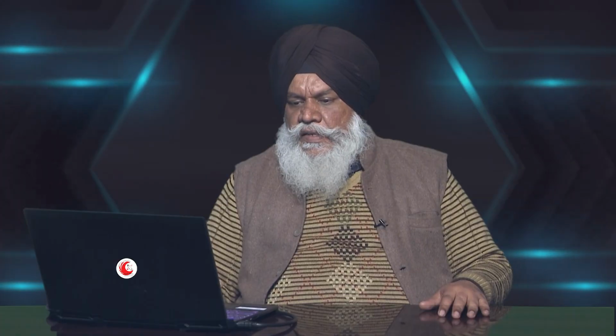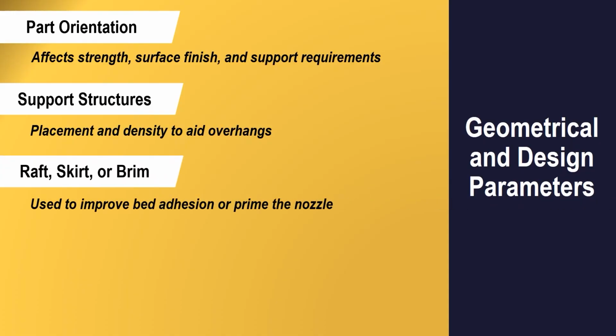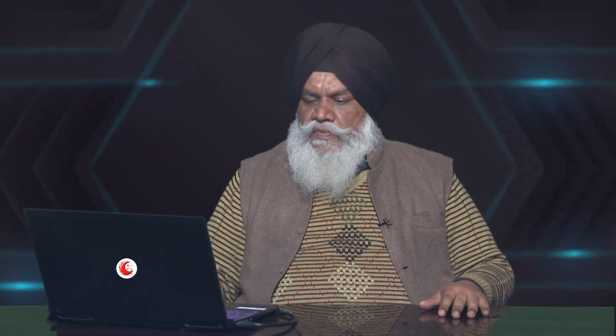So the density, to aid any overhanging part, that is really important for these types of support structures. I can keep it at a lower value. Then the raft, skirt, or brim, this is used to improve the bed adhesion or basically the priming of the nozzle.